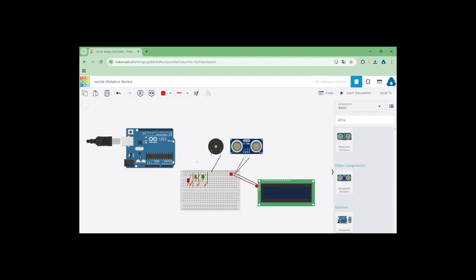In 5 volts. Also, the most important is that 5 volts will connect with the positive way, and GND will connect with GND. With the situation that we have now, GND black goes to the 3 LEDs, the pulsar, the ultrasonic element, and also the LCD. And with the 5 volts, we do the same.